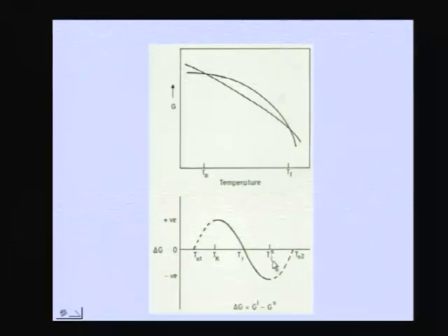is no more stable. But anyway, this is a temperature which is only theoretically possible, and practically reaching this temperature is very difficult. So usually in textbooks you don't come across this. There are a lot of people doing research in this area, but basically you do not talk about this, whereas TK is to some extent achievable, and in a number of systems we have achieved the liquid and glass condition below the TK or TG, whatever you want to call it. Some people refer to it as TG, glass transition temperature, some people call it TK, the Kauzmann temperature, but both are basically the same.